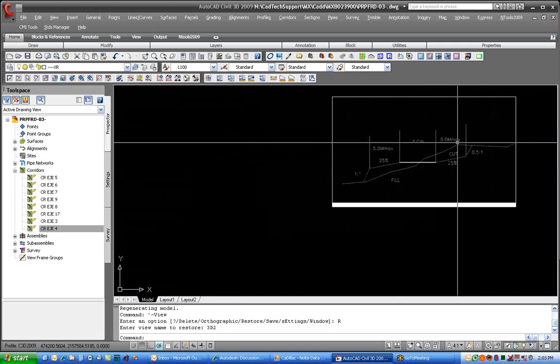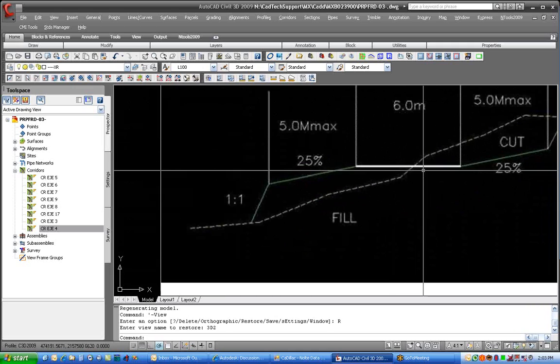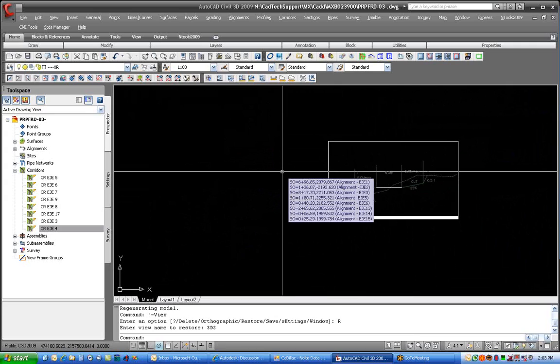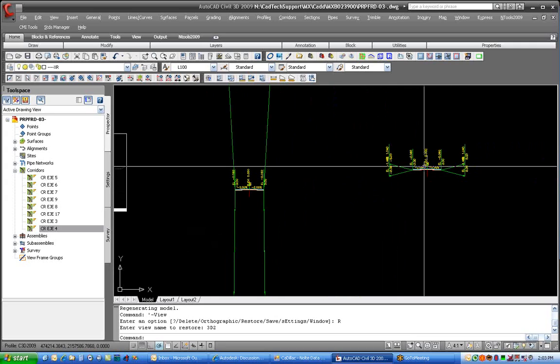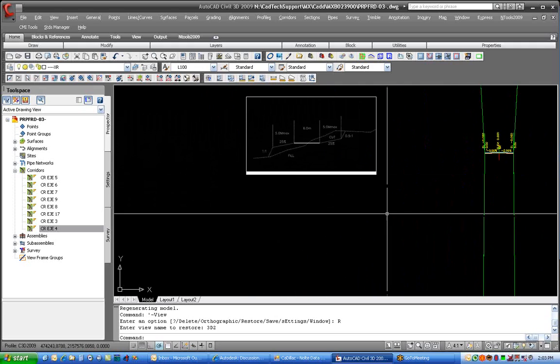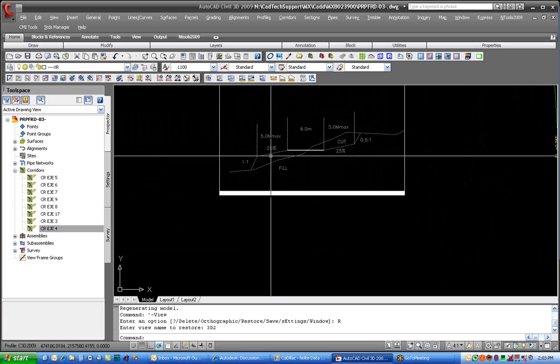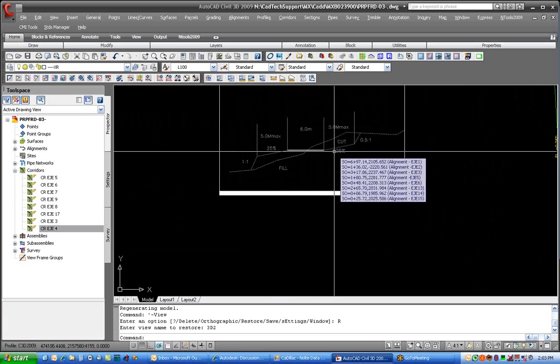So interesting stuff. What I'm going to do is build, I'm going to put a crown on it. He just sent this as a quick example of what they're trying to do. So I'm going to do this similar to this one, but I'm going to do it using the conditional elements so I can check to see whether it's in cut or whether it's in fill. And I'm actually going to do it twice to expand on some of the concepts here.